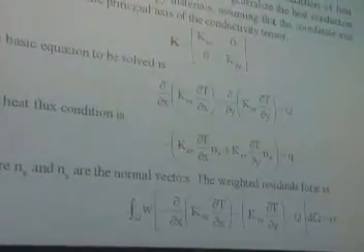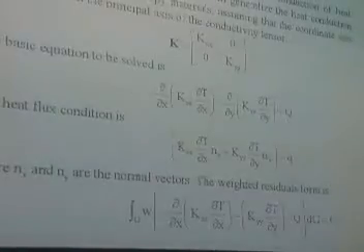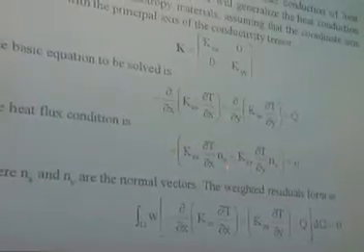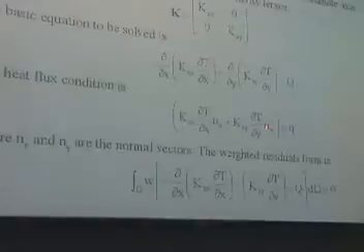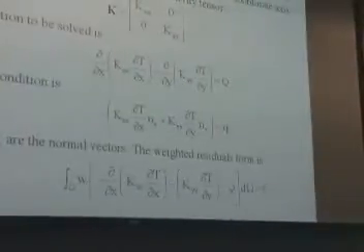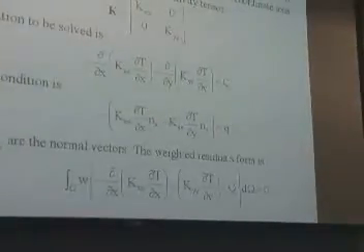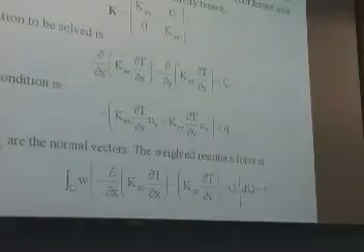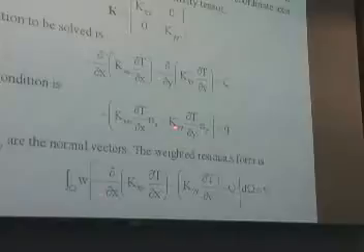I'm now dealing with the surface. So it's just different from 1D where I just had this term. Those n's, nx and ny, are the normals to the surface because the flux is normal to the surface, so you use sines and cosines in geometry to calculate the normal flux, the direction. That's easy to set up and can be done quickly in a code.